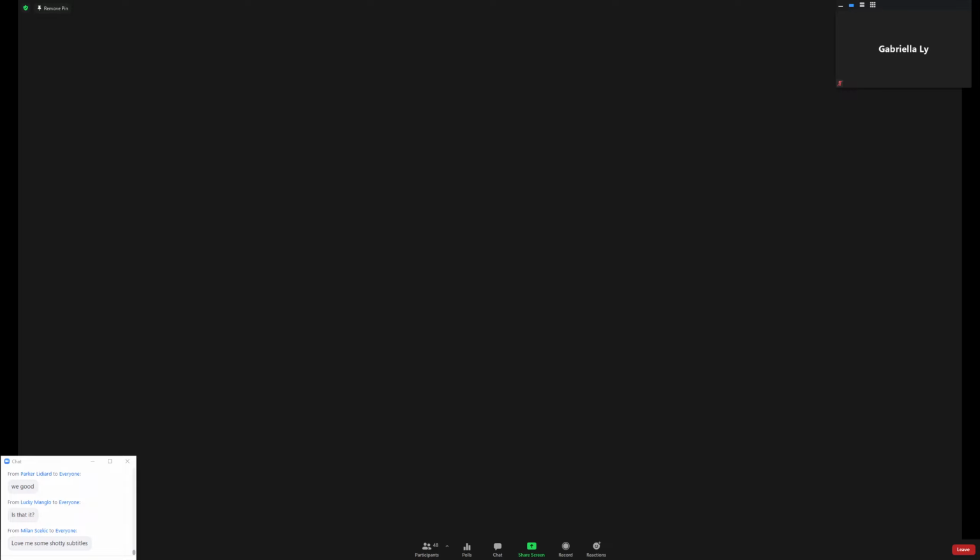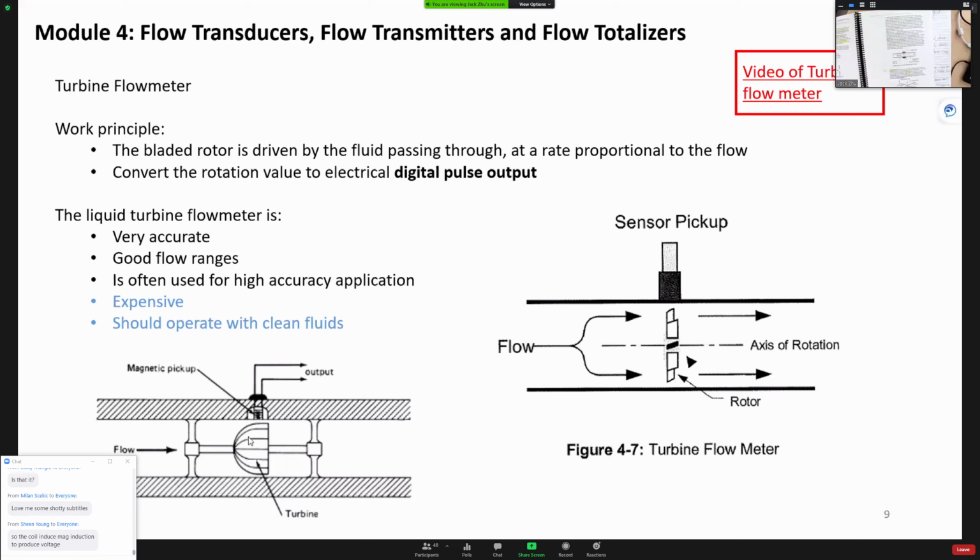Okay, so I think the video explained better than me, right? So they use the metal blade down here. Each blade is called a paramagnetic blade. So these have a magnetic pickup. Each time the blade passes through that magnetic pickup, it will induce a voltage in the sensor, and the sensor is going to receive a signal just like a generator. You can generate a voltage waveform, but for that voltage waveform, they use signal conditioning to change it to a square wave for better processing and calculation.